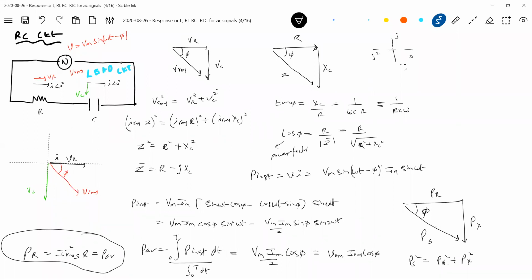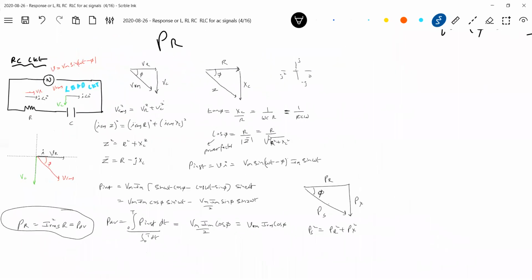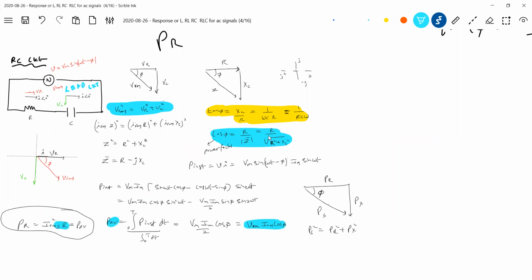So this is called a lead circuit, and there's a lag circuit. These are the basics here. I'm bringing the whole set of formulas together in one place. All are very important, because when you go for numericals, you'll see that these equations are going to help you a lot. Then writing KVL, then power dissipation, average power, and who will dissipate power here? Only the resistor will dissipate power. Write it very clearly: only the resistor dissipates power in an AC circuit. Finish over.